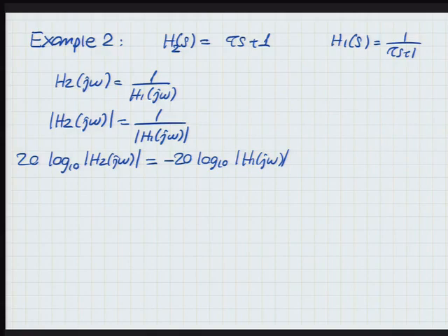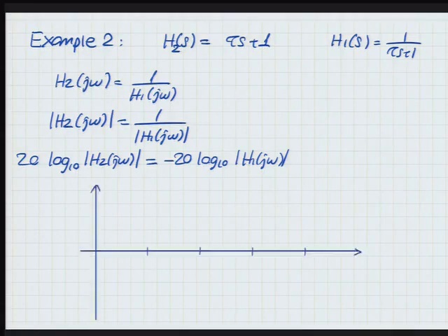So now we're looking at the magnitude again. That was 1 over tau, right? So up to that point, again, it will be 0 dBs. Let's make it more solid. Okay, so 0 dB up to that point. And then it grows by 20 decibels every decade.